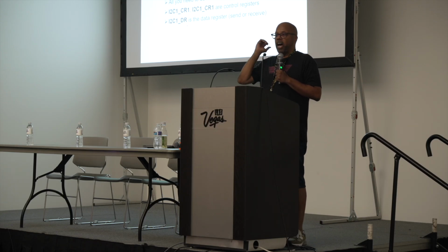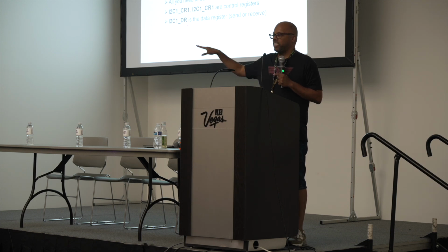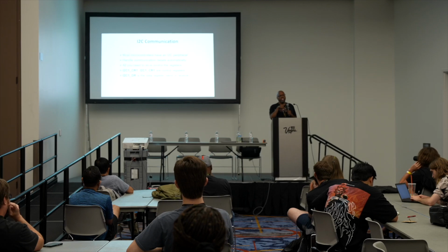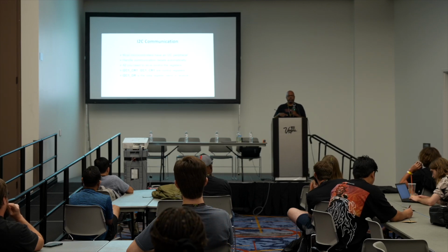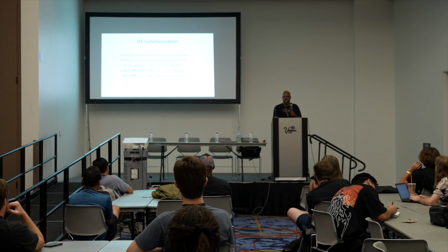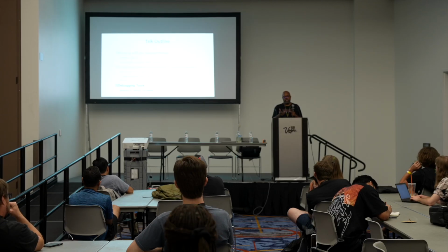Also, I2C DR is its data register. So if I want to write a byte on I2C, I want to send a byte, I write it into the DR register, and it'll get sent, right? So you don't have to know I2C. You just have to know, oh, if I write into this DR register, it will get sent, right? And on the receiving end, if I read from this DR register, I will receive whatever was sent, okay? So there's hardware built in that deals with all the details of the protocol.